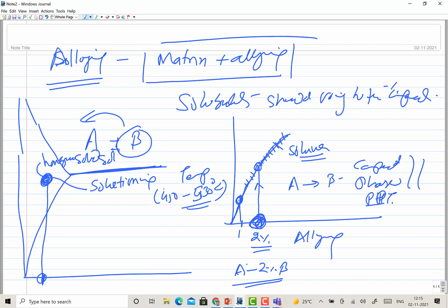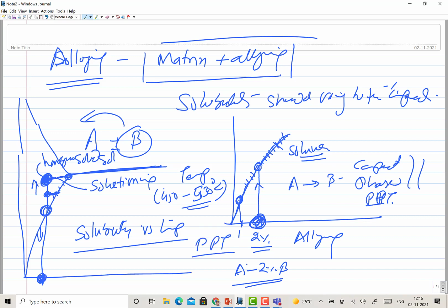Okay, since this is at a high temperature where it can dissolve more, this is the solvus line, which means at this temperature it can hold this much of the alloying element, at this temperature it can hold this much. So basically you are forming the solid solution at a high temperature. If the temperature is too high, it will accommodate all the alloying elements. So this is the temperature at which the alloying elements get dissolved and form the saturated solid solution. Above this it will be undersaturated, and below this it will be oversaturated. So the change in solubility as a function of temperature is crucial in precipitation hardening. What we are doing is taking the alloy and heating it so that it forms the homogeneous solid solution.